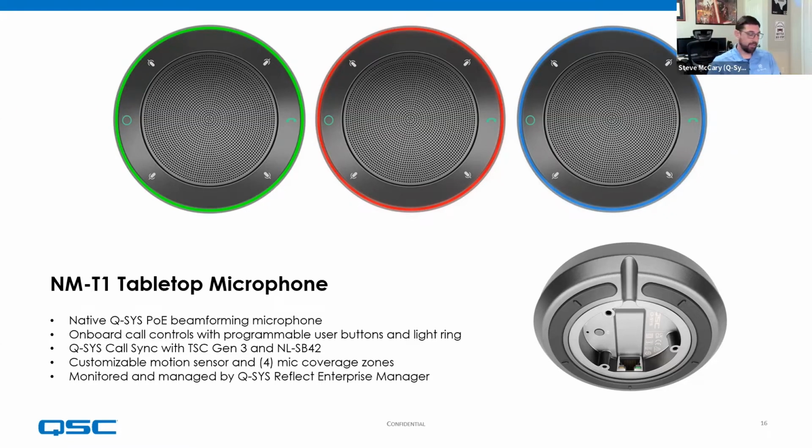Yeah, there's a beam orientation, and that really just has to do with whether the beam is centered on the microphone button, or exists between the 2 buttons. So there's an orientation that you can change, and then there is the typical AEC tail length that you can adjust as well. You can have it as 200 milliseconds, or I think 200, 300, or 400. That'll change the amount of processing that it requires as well. Gotcha, we'll dig into all that fun stuff when the time comes.